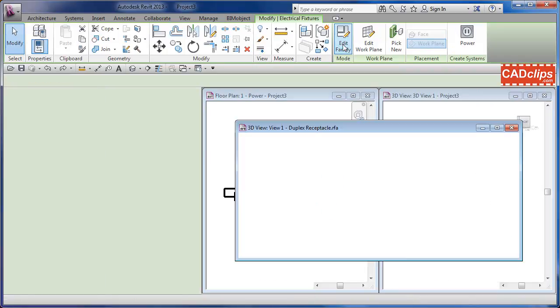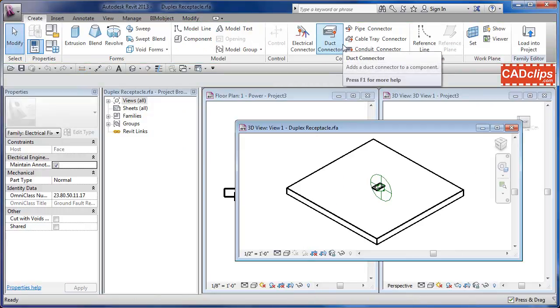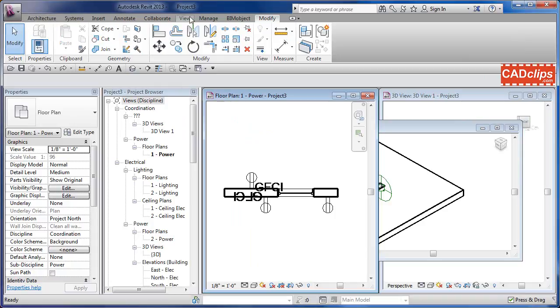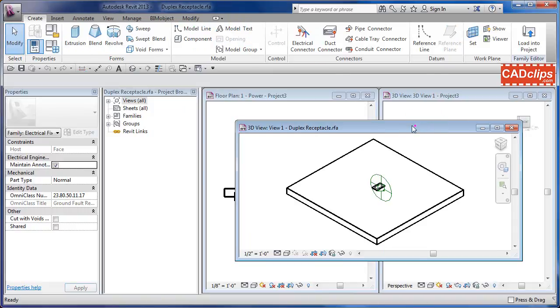Now I'm going into a special kind of flavor of Revit where I am opening up the family. And you'll notice that your ribbon in your menu here looks different. Look at the way the menu system is. Now watch when I pick in here. All of a sudden, I'm going to get more tabs and more options, because this is the project environment. This is the family editing environment.